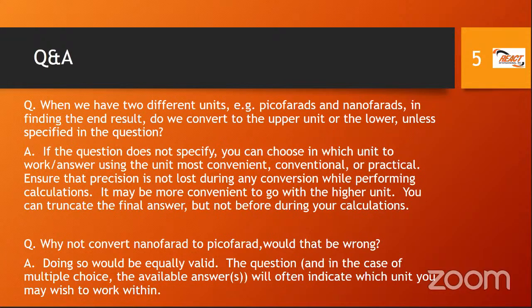Now, the second question is related to the first, and it goes a little further. The question is, why not convert nanofarad to picofarad? Would that be wrong? Because in the example that we did, we actually converted from picofarad to nanofarad. These two questions are excellent questions that were asked by the participants. So there's nothing wrong with converting from nanofarad, the units that were given, to picofarad and then calculating. In other words, doing so would have been equally valid.